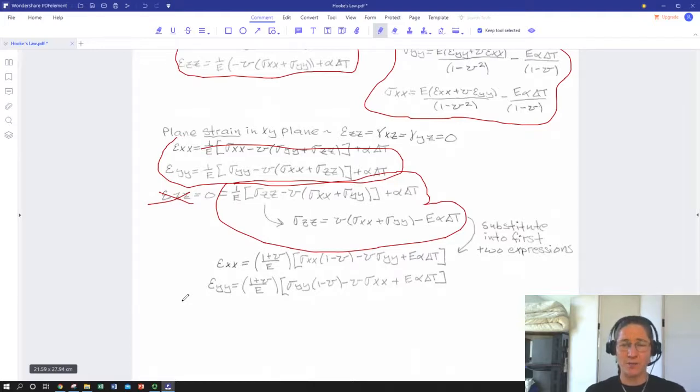And then simply be able to understand how not to mix up plane stress and plane strain. Plane stress means you have stress in only two directions. Plane strain means you only have strain in two directions, and you will, guaranteed, end up having the opposite in that third direction. Plane stress will result in you having strain in that unconstrained direction, and plane strain is achieved by having stress in all three directions. Otherwise, Hooke's law is just a matter of application.